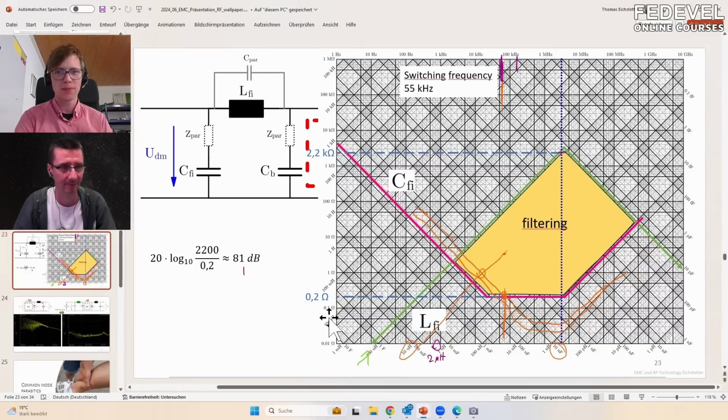Heat means you have a chemical reaction, and then your circuit is, let's say, aging more when you have a higher temperature. And when you have a ceramic capacitor, then you have less ESR, less heat, and then it lasts longer.